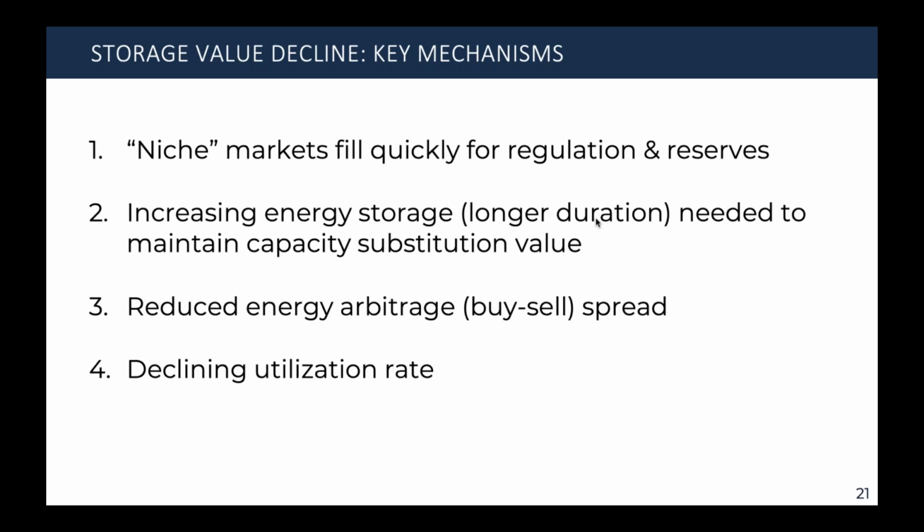But as you start to eat down into the gas capacity further and further, you'll find power plants that run for longer periods of time and more frequently. And therefore, if storage is to displace their capacity, you need to have 8, 10, 12, 16 hours of storage duration in order to continue to displace the capacity from those technologies.